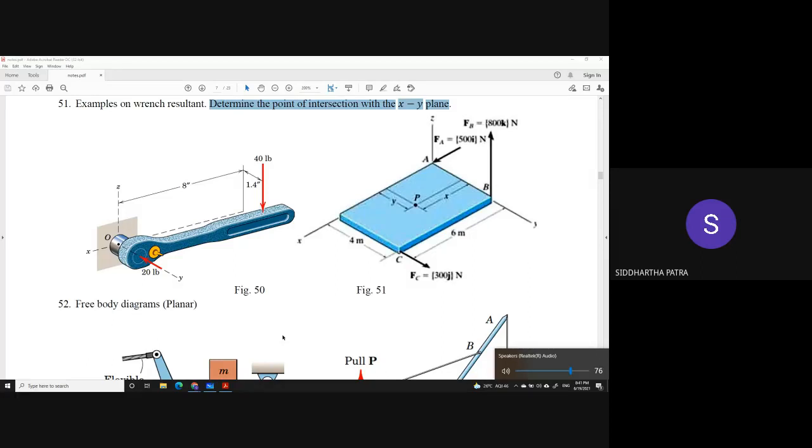And then we know that we can represent the system with a single force, because the M parallel is 0. Now the range resultant is a superset of that single force resultant, which means the single force resultant has M parallel equal to 0, but the range resultant does have a non-zero M parallel.